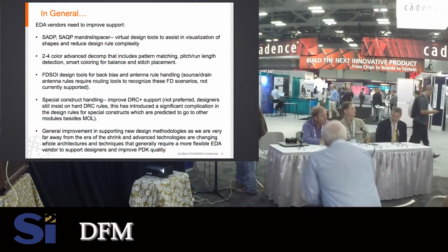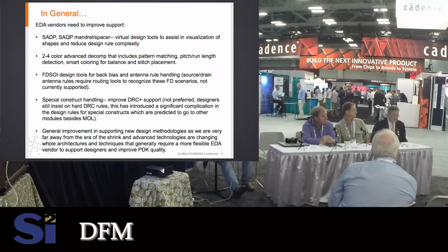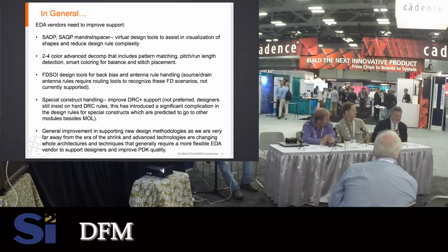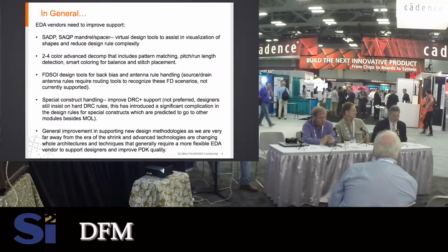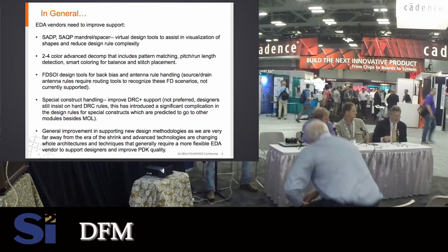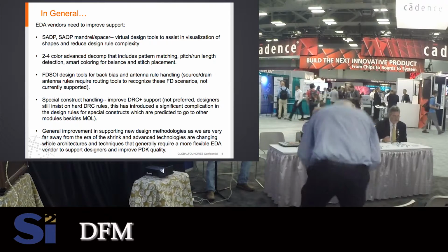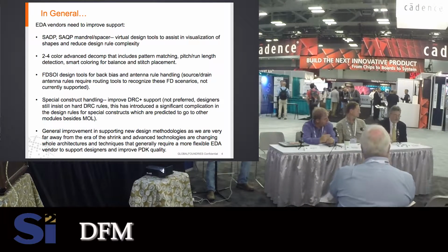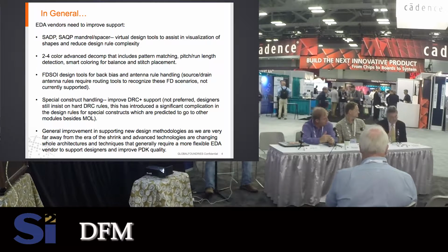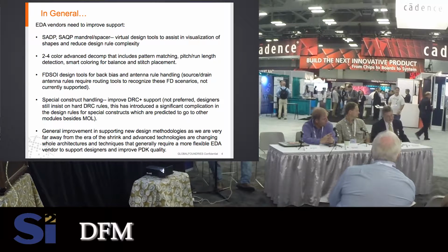Well, as I said, we think that the main mechanisms that you need to use to develop rules are, one, to cope with the complexity of the rules, and that has to do with being able to execute them. So if you design a rule, that becomes an executable in the sense that you can run your design rule check right away and keep changing the rules, and you can generate patterns that conform to the rule or that violate the rule, to check if that is what you mean.